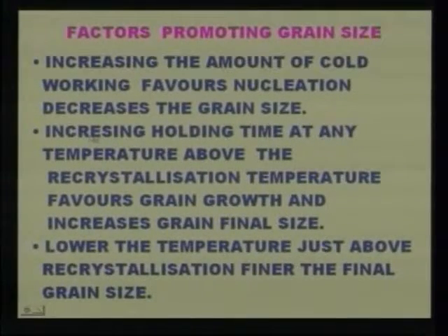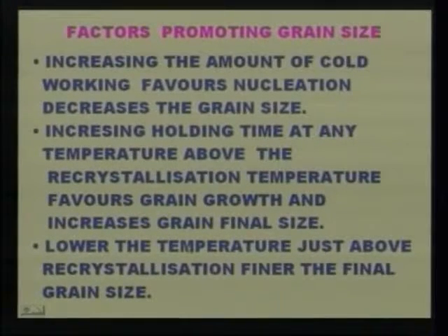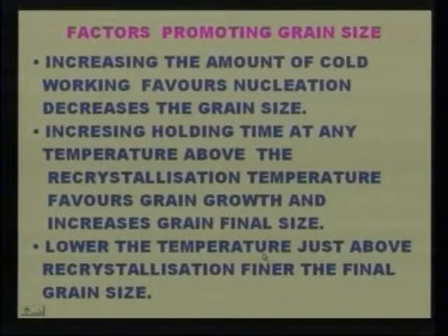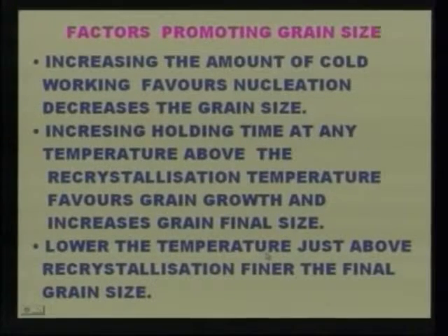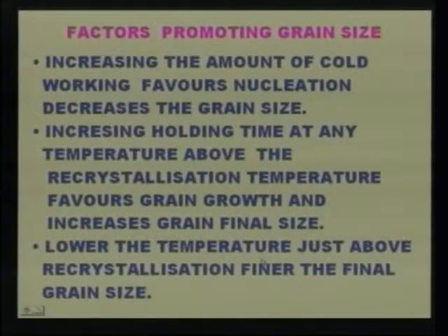Now see another factor: increasing the holding time at any temperature above the recrystallization temperature favors grain growth and increases the final grain size. Another factor: the lower the temperature just above recrystallization, the finer the final grain size. By lowering the temperature just above recrystallization, we can reduce the grain size, so we can promote the finer grain material.